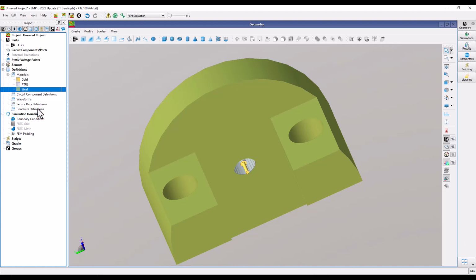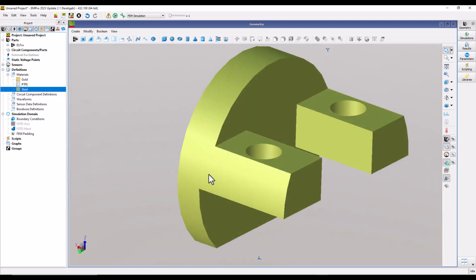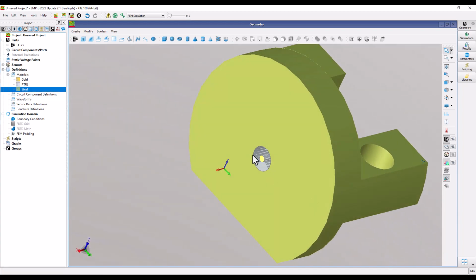So here I'm going to save this project. Before I do that, I would also like to assign a coax feed here or waveguide port. It will serve two purposes. One, we can apply the waveguide port and then simulate the port to make sure it indeed is a 50 ohm port as we are hoping. And then this port can be accessed in ADS to provide the termination with the rest of the circuit design or assembly design that you're doing.